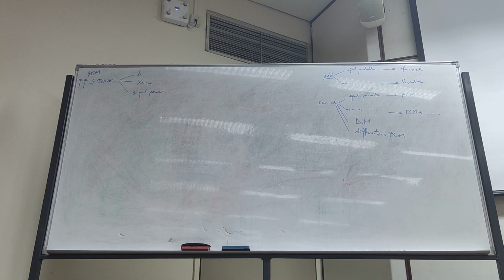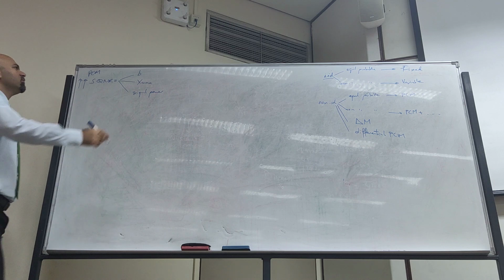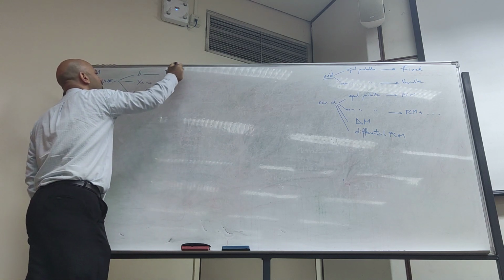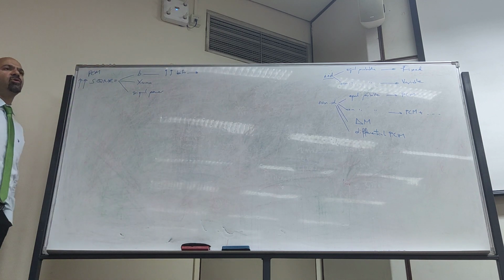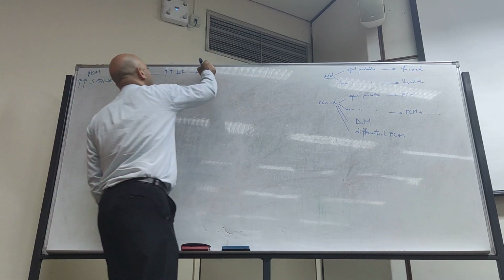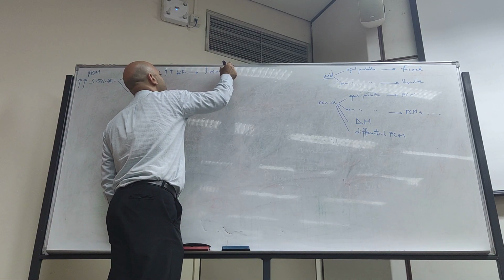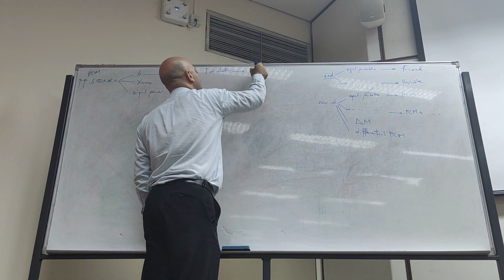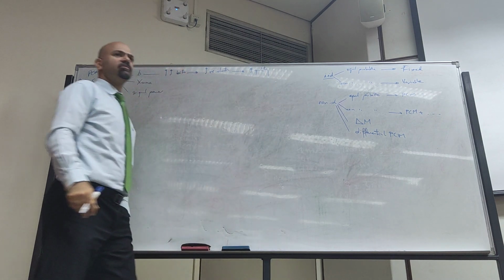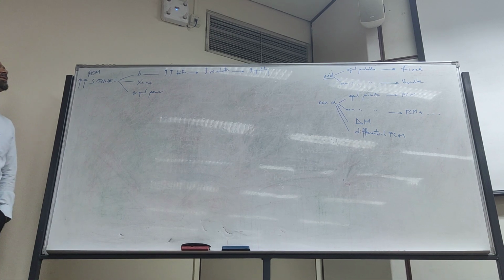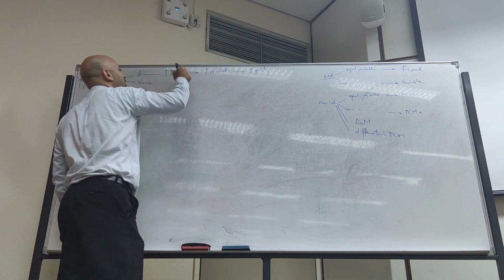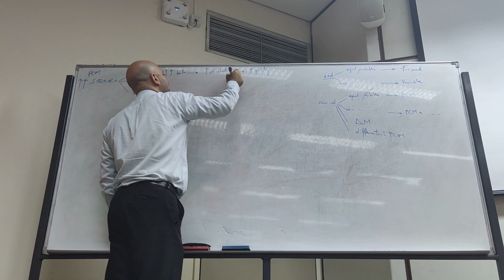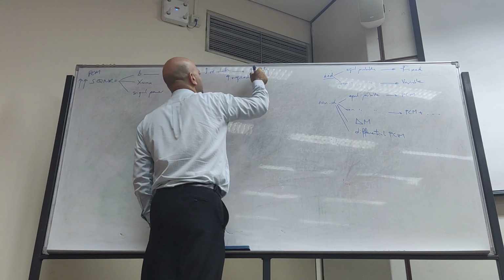So what to do? With the B, obviously, whenever we increase the number of consumed bits, we will achieve more resolution, especially if it's video, which means more quality, right? But we know that increasing the B is not for free, like everything in engineering. What is the drawback? Cost. That's it. The bad thing is that we also increase the required data rate or cost.